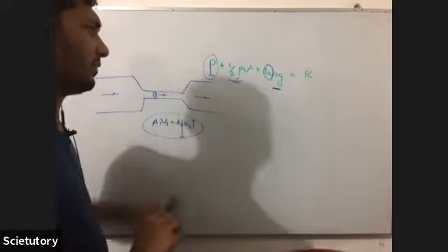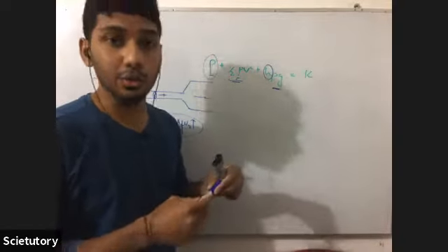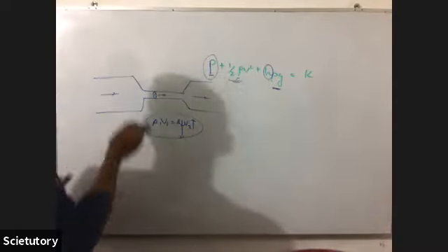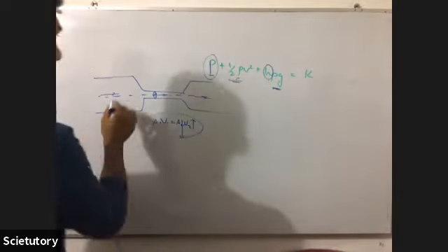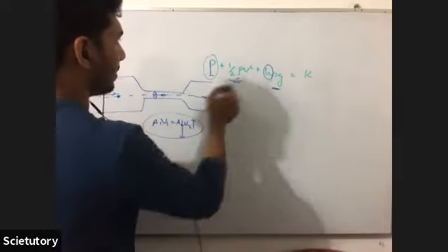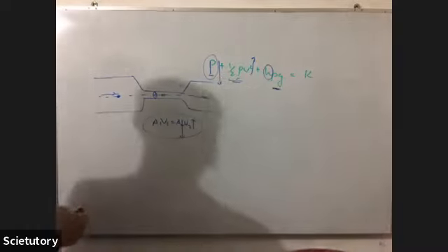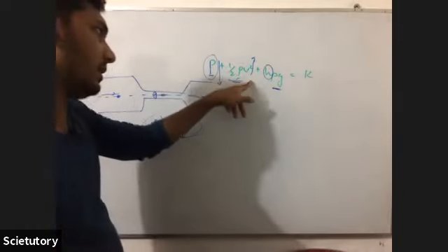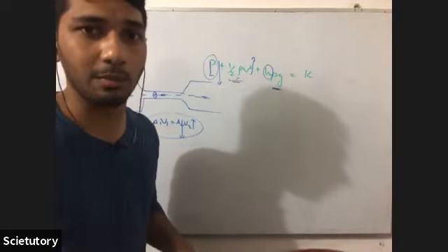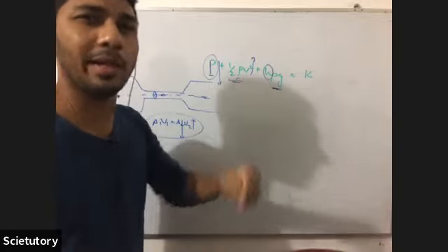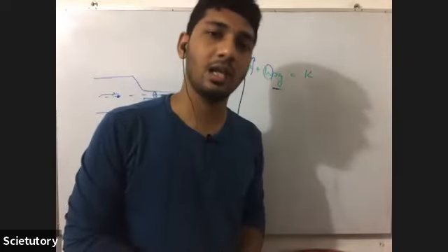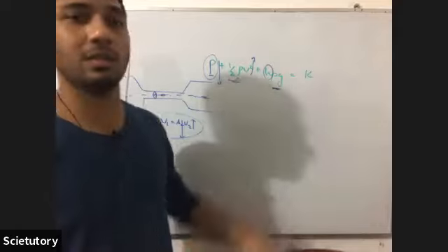So if you analyze that particular scenario using Bernoulli's equation, H is constant. When you consider a streamline like this, there is no difference in H when you compare this part of the liquid and this part of the liquid. But the V is increased, so P should reduce. If they talk about the velocity and also the pressure, that is explainable by Bernoulli's theorem. But they are only mentioning the change in the velocity, so that is explained using the continuity equation. There is no job for Bernoulli's equation here.